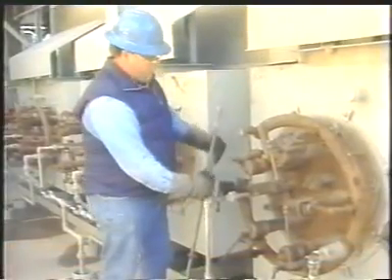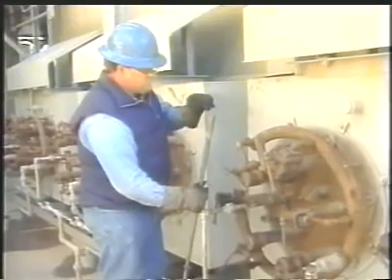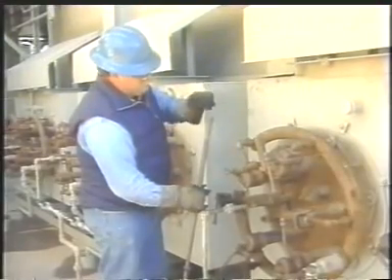Erratic flame pattern and a puffing sound from the furnace indicates loss of draft and a serious shortage of oxygen. The flames may start burning out of the heater in cracks where air enters. This is a hazardous situation which can damage the furnace. Puffing and woofing can also be caused by flame instability due to burner damage or by too high a fuel pressure.